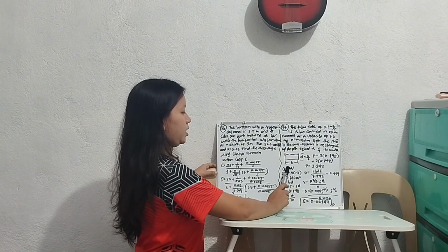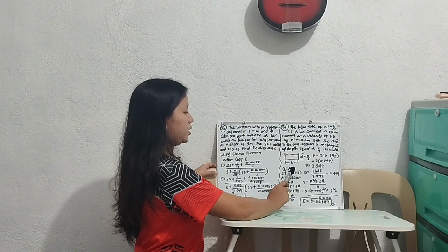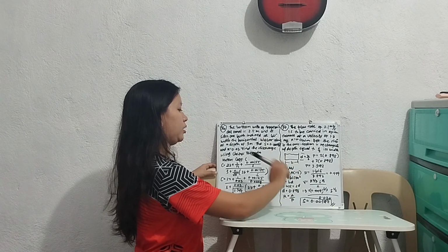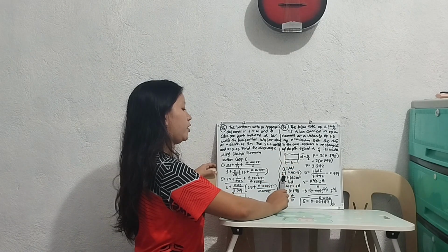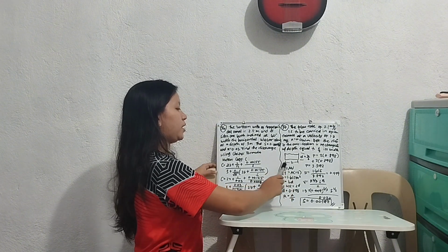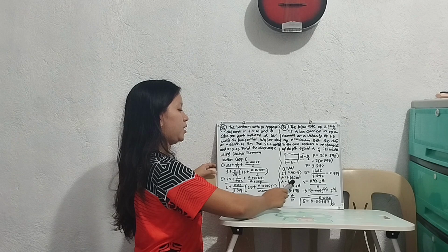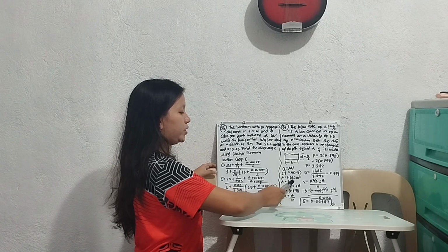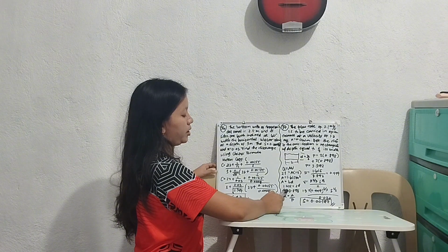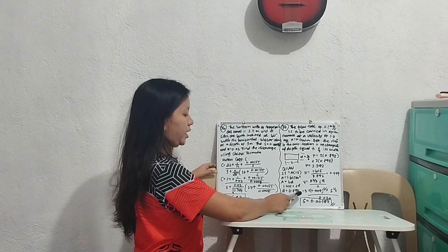So we have the discharge of 2.1 equals area times the velocity, which is 1.3. So you calculate that, we came up with an answer of area is equal to 1.615 square meter. The area is the base times D, so we have the area of 1.615 equals 2D. So we came up with the answer of D, which is 0.898.